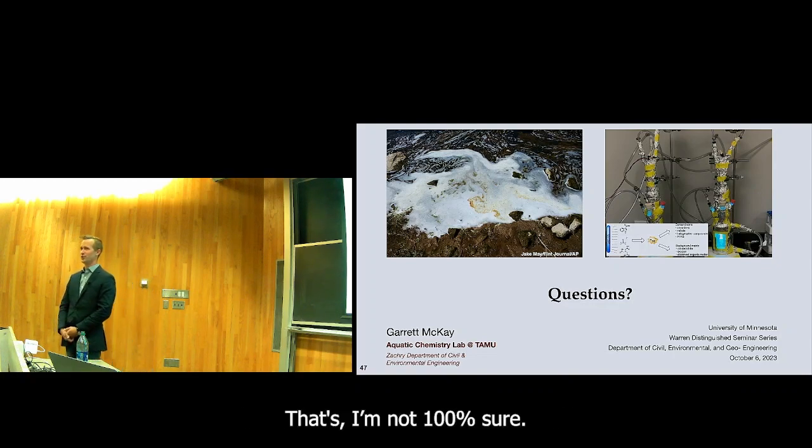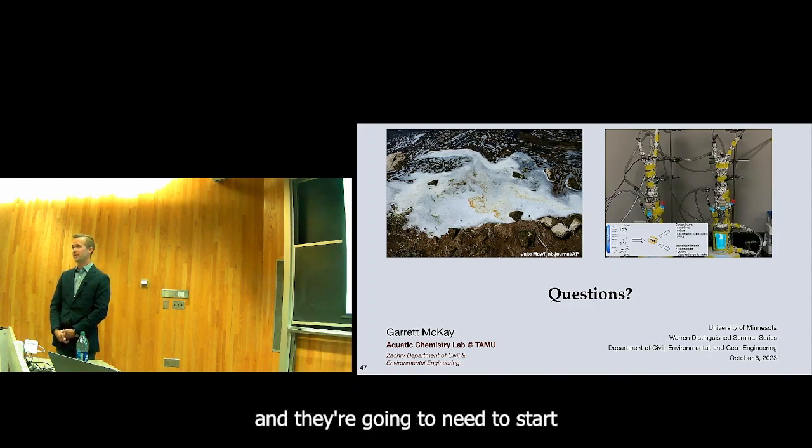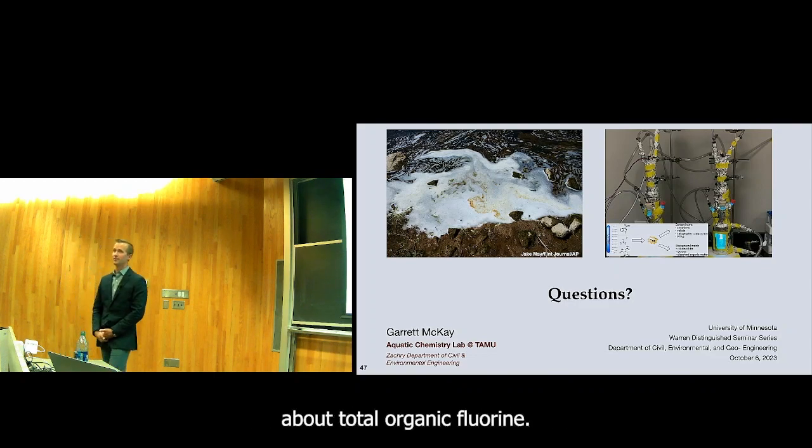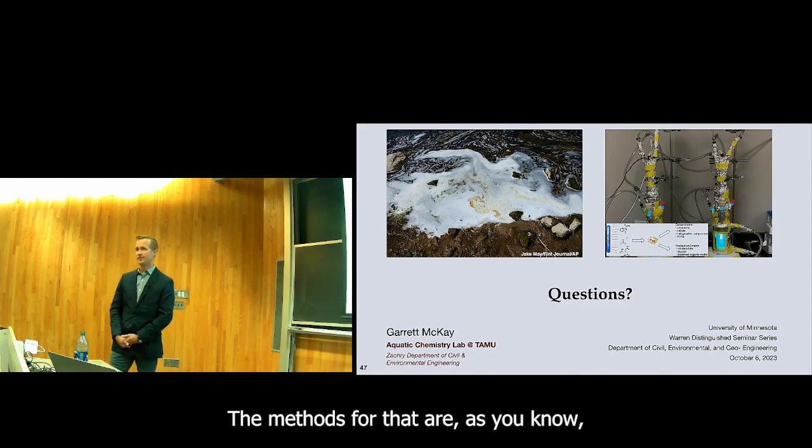I'm not 100% sure, because there are destruction technologies out there being piloted, and they're going to need to start being used a lot more as all these DoD sites get cleaned up. I imagine the ultimate goal is that your waste doesn't go into a hazardous waste landfill. You could somehow discharge, but whether that's achievable with any of these, I'm not 100% sure. If you needed to meet discharge for fluoride, you could just dilute with some other water prior to discharge. But then again, you're having to worry about total organic fluorine. The methods for that don't have as low a detection limit as individual PFAS, so that's a challenge too.